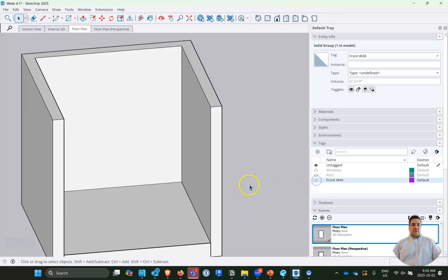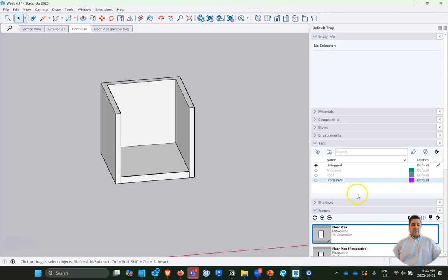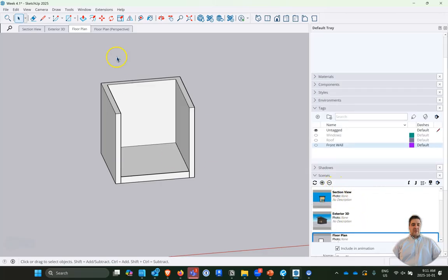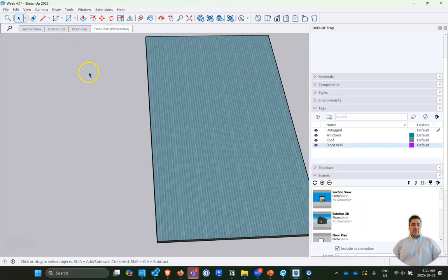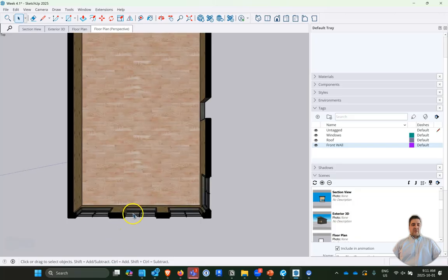And we can just turn off that wall when we want to see in our building. So if you have views that you're trying to set up to show different things, then tagging is a way to potentially hide certain walls if you're trying to show that or not show that in a camera view. And when you go to your settings for your different camera views here, you could certainly apply those tags to different elements.